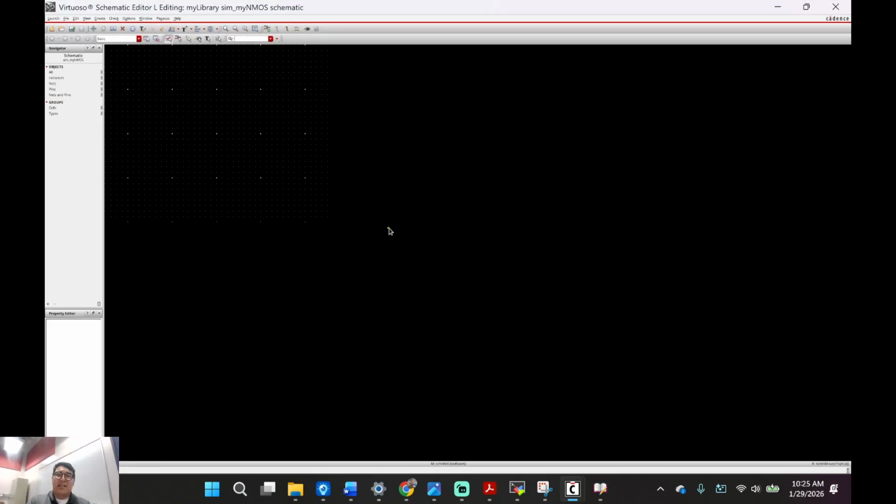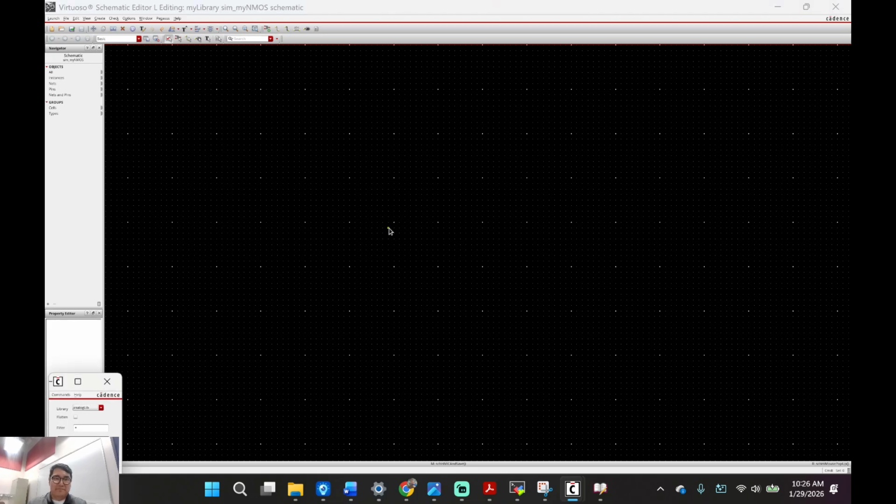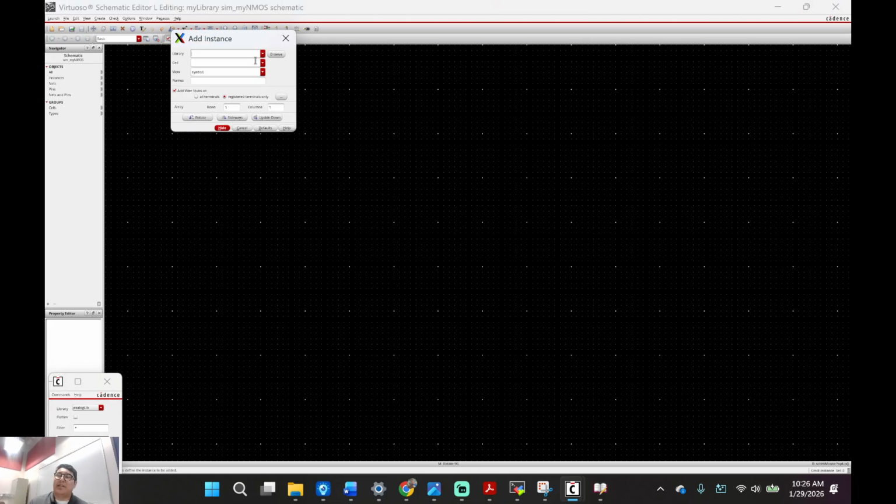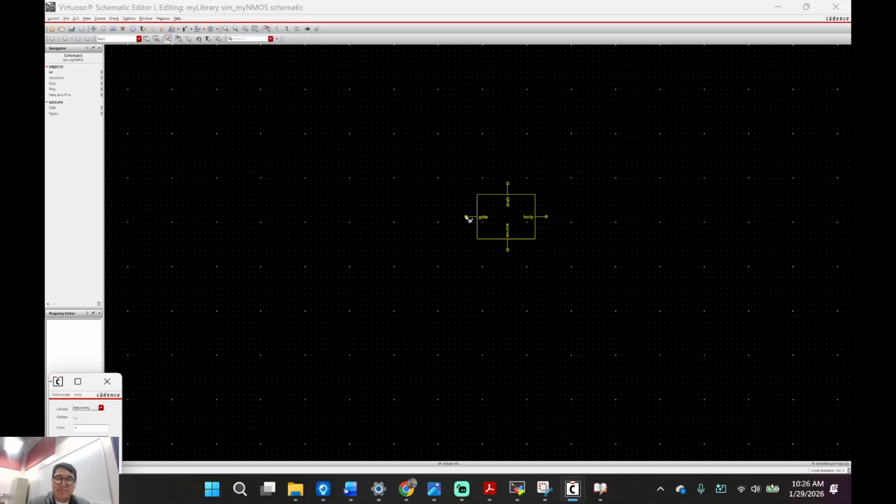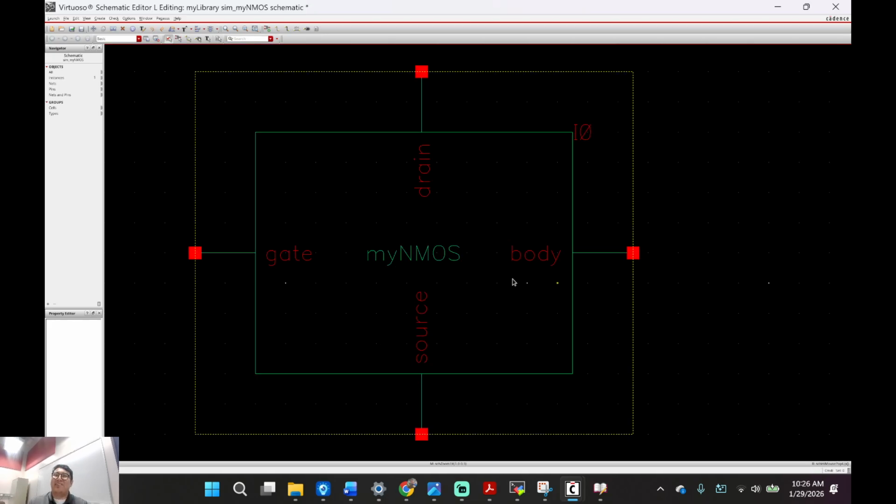Anyways, now that you have your sim, okay, press I. Just press I. And we're gonna add an instance, okay? Go to your library, which is called My Library, okay? Click on it. You're gonna go to your cell. My NMOS, okay, there it is. My NMOS, okay. Hide. And boom. You guys like that? It's your NMOS. It's kind of ugly, huh?